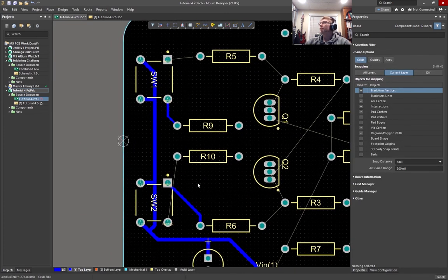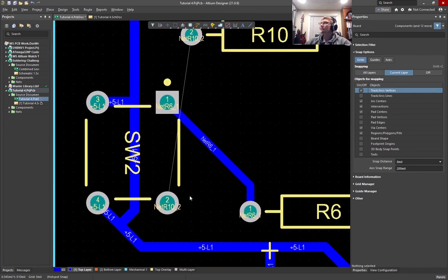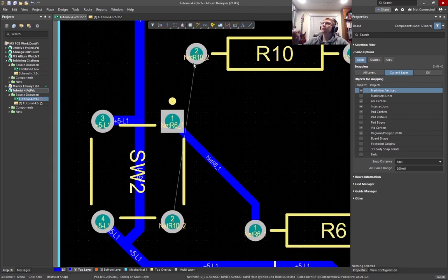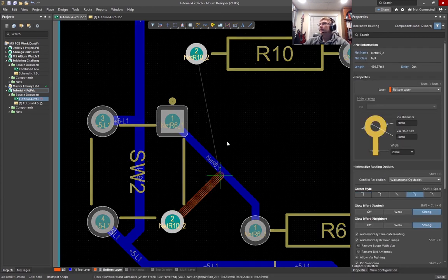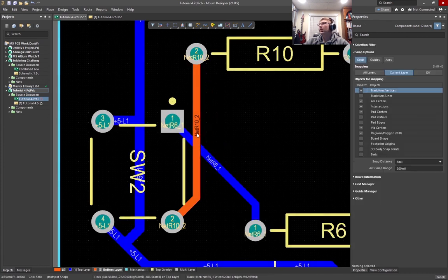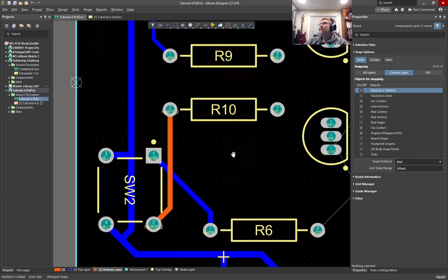So one thing that I'm noticing right away is I have some nets that cross each other. And there's a couple ways to deal with this, but the easiest way is to leverage the fact that these holes actually go through the PCB and out the other side, which means that I can use the bottom layer to route them. So if I hit asterisk on my keyboard, I switch to my bottom layer. I can also just select the bottom layer, Control W, and now these traces are on the other side of the PCB, so I can actually cross them and they won't make electrical contact.